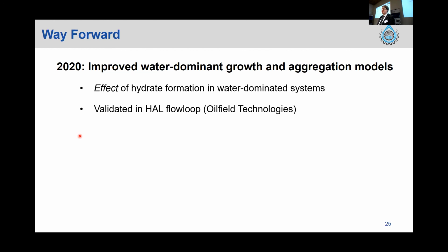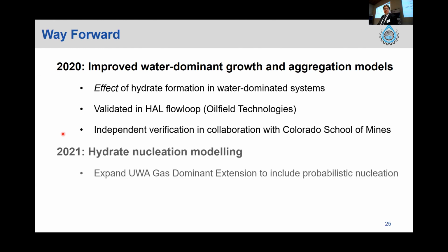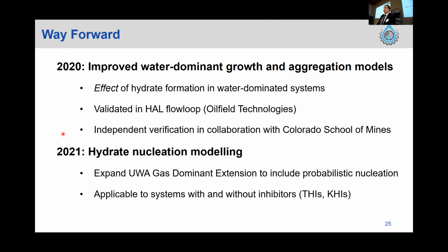So we have a PhD student working on that. And then we also have done some work with the Colorado School of Mines in their high pressure water tunnel, looking at trying to clarify what the surface area of bubbles in these systems looks like. And then the second major thing next year is we want to take a look at the idea of hydrate nucleation modeling and trying to get some way of describing that within the OLGA extension itself to include probabilistic nucleation. And this should be something that we do for systems which have both THIs and KHIs.